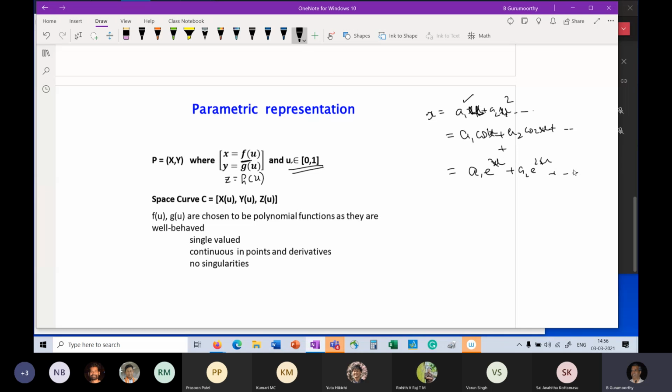Okay, so please note this. This is the parametric variable u. So a1u, a2u square and so forth. So the first thing is that with the polynomial function, you're always guaranteed a unique value back. No matter what u is, no matter what a1, a2, a3 are all chosen to be, if you plug a value of u, you'll get a unique value of x back. And that is very desirable, right? That you want your function to be single valued.